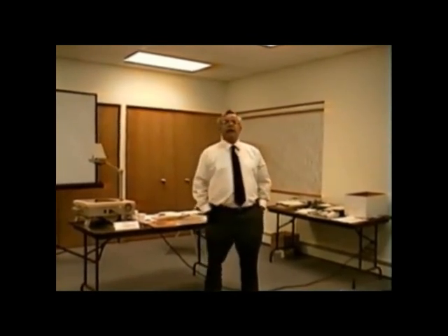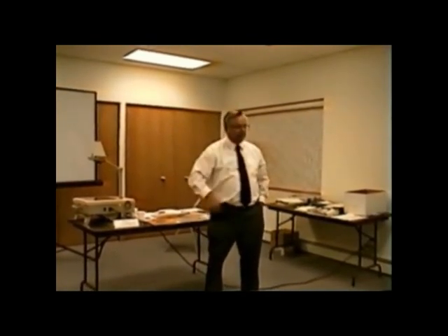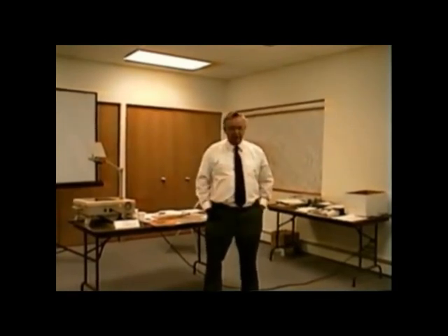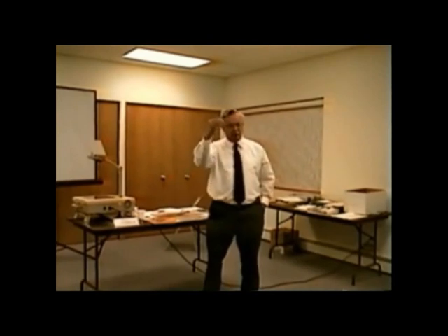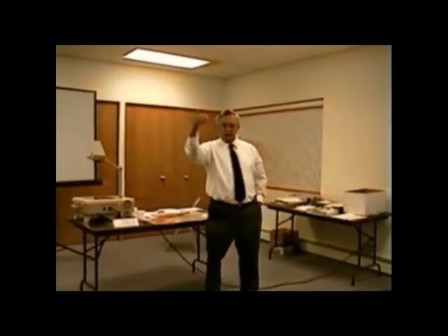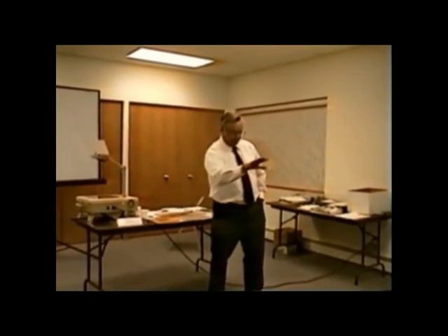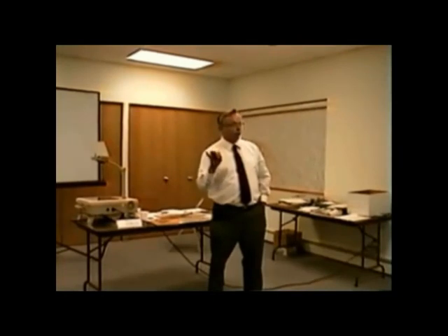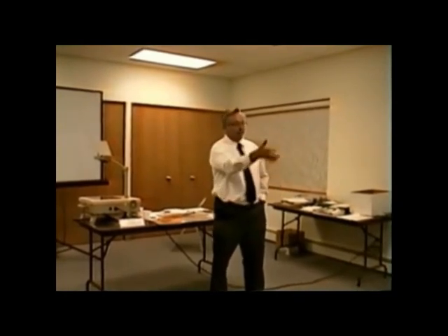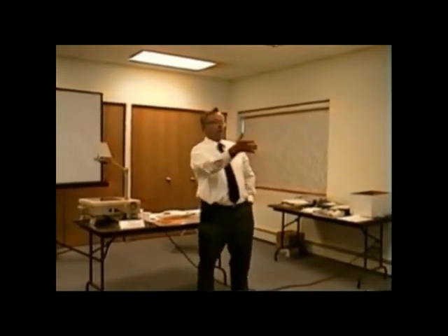The same thing happens with the gas range. Mrs. Jones, would you please turn on all the 4 burners and the oven? And you have to stand by the range because that's a lot of heat coming out, but we have to have all of it on. And then now we go back to Mr. Jones and the water heater, because, ladies and gentlemen, we could have the furnace on, let's say at Thanksgiving Day, and the customer is using all 4 burners and the oven. They're drying clothes and they're taking a shower. Different people doing different things, but the point is they're taking a shower.